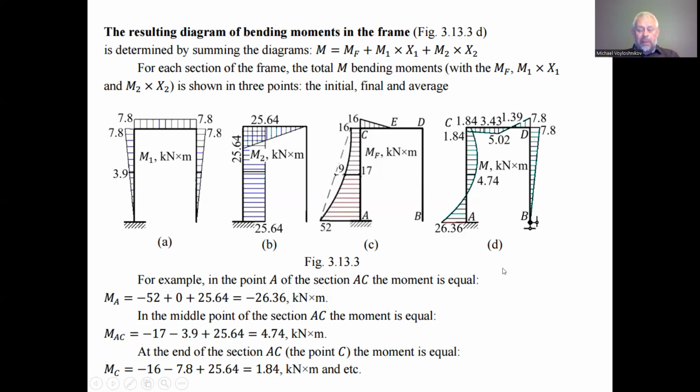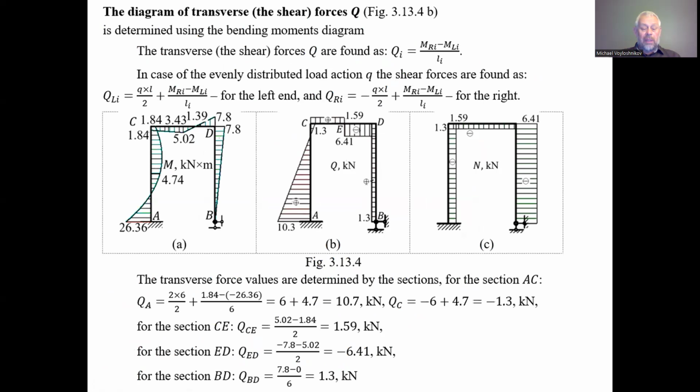After that, we have to remember that we are assigned to find the diagram of the transverse forces and the longitudinal forces. To find the diagram of the transverse forces, we use the mathematical property of the diagrams of bending moments and transverse forces, as these diagrams are in a derivative-integral dependence. For each element of the mechanical system, the diagram of the bending moment is the integral of the diagram of the transverse forces. Accordingly, the diagram of the transverse forces is the derivative of the diagram of the bending moments.